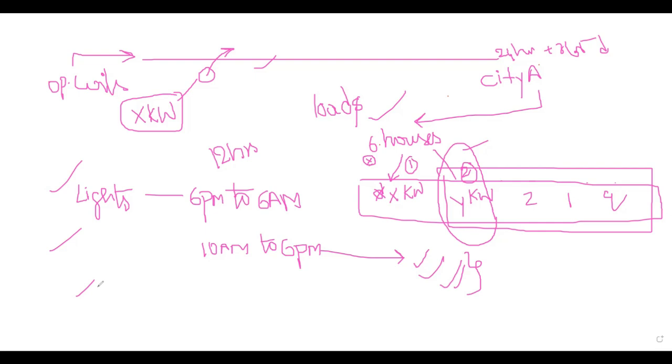And apart from this, we have some loads which we call momentary loads. Momentary loads are like the operation of the circuit breaker and the operation of the isolator, which will exist only for 1 minute, maximum 1 minute. The opening time or closing time of a breaker is 60 milliseconds to 120 milliseconds. So loads like breaker operation and isolator operation, we call momentary loads.